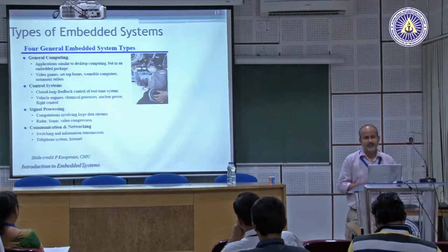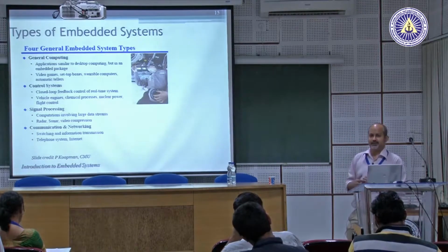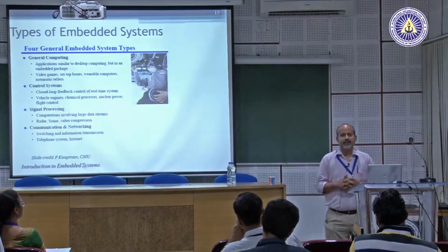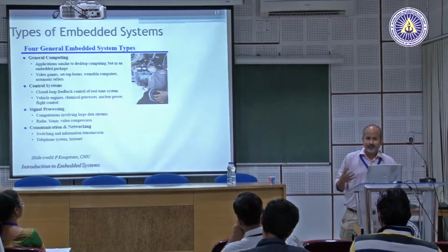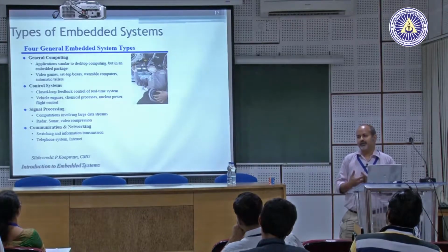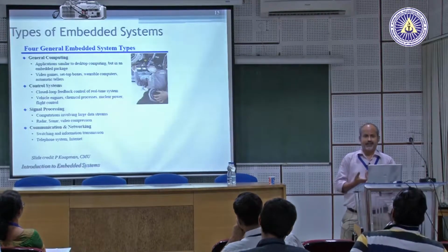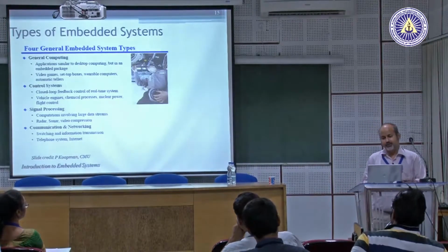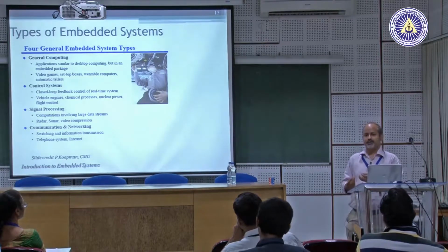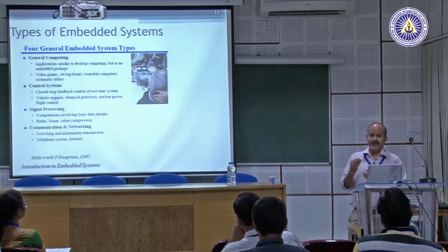Open loop control are simple things, but whenever you have closed loop control, you have sensors and actuators in the system, right. And the sensors are the ones that tell you about the current state of your system through some measurements. And from those measurements, you construct what is called a state estimation. You try to understand your system state, and when you estimate your state, then you know exactly what you have to do to change the state, so that you are closer to where you want to be, because there is a control trajectory that you want to be in order to make things work.